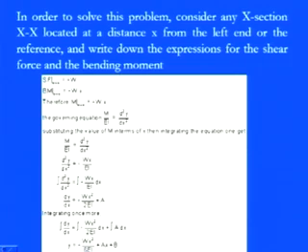So, shear force at the XX section is nothing but equals to minus W. For the bending moment, since it is going in the downward direction, the hogging one, the negative direction applies again as per the sign convention of the bending moment. So, bending moment at the XX section is minus W into x. Therefore, the bending moment is nothing but equals to minus W into x for the XX section. Go for the first equation, which is M by EI is equals to d2y by dx square.